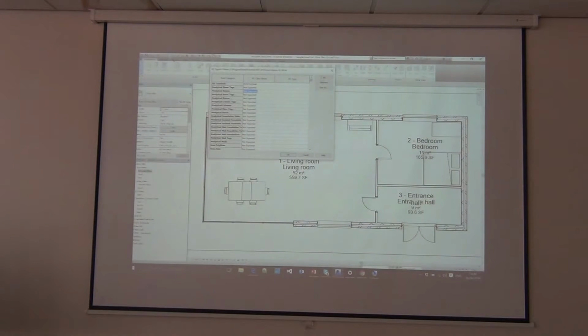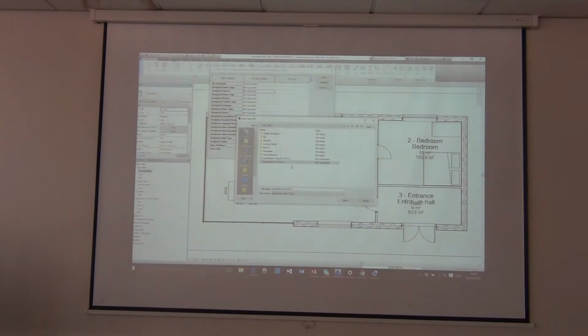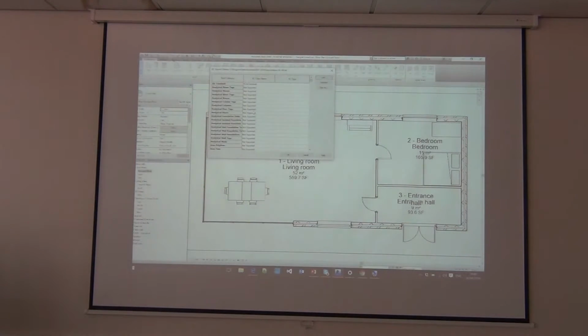And that can change. So if I go here and load, here I've got export layers for changing to British Standard 1192 conventions. Here's export layers for IFC itself. And if I open that, it changes all the mappings of these things. So when we look down here, we'll see now that furniture is mapped to a system furniture element in IFC terms.